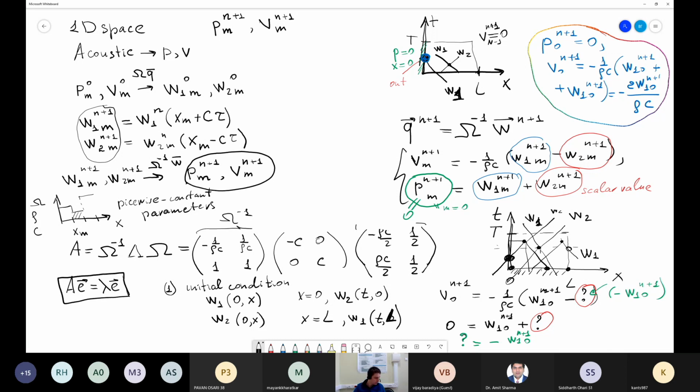So now we can pose any boundary conditions. Fixed boundary conditions, velocity is equal to 0; free surface condition, pressure is equal to 0; some non-reflecting boundary condition, when we say that we have to obtain only the waves that go out from our domain, and we will try to combine the value of velocity and pressure to obtain zero reflection coefficient at this boundary.